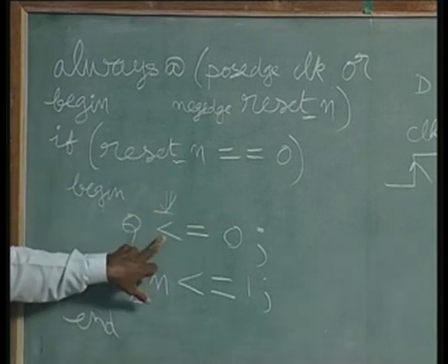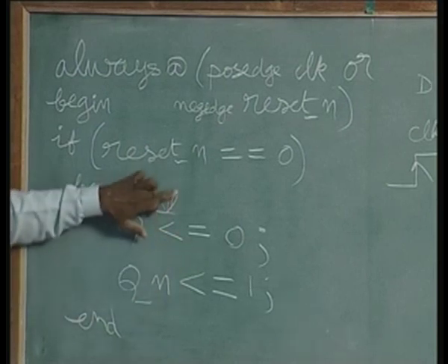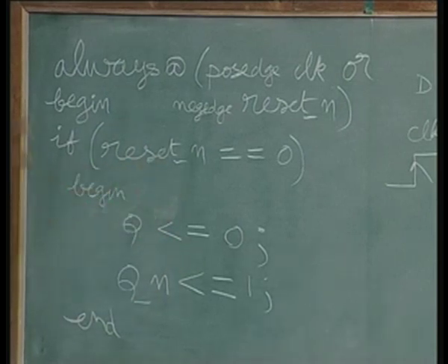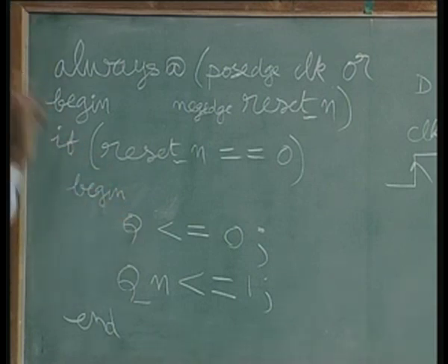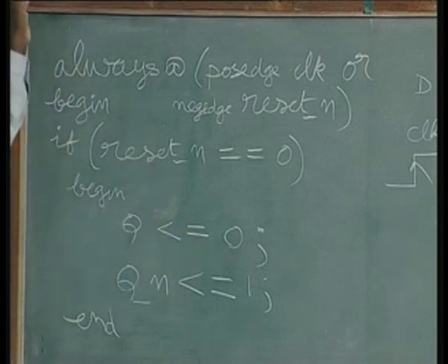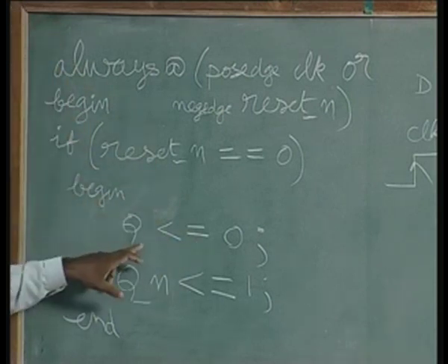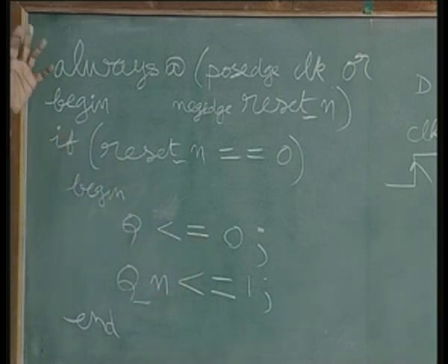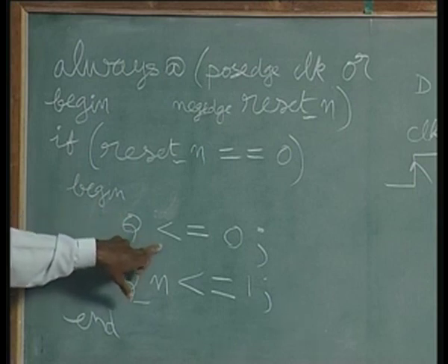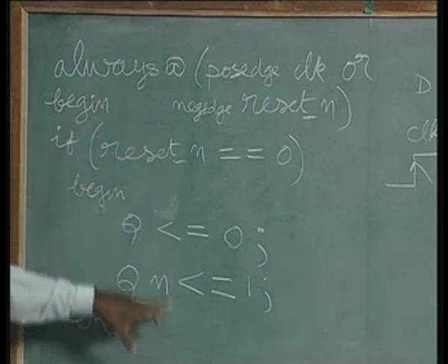It is not less, you have to read this together. So, this equal to distinguishes assign statements and this. In assign you had used plain equal to, all combinational you use that, and here you have to use what is called a non-blocking statement. The earlier one is called blocking statement. And if you do not put this one, again the tool will complain. So, take care of this.